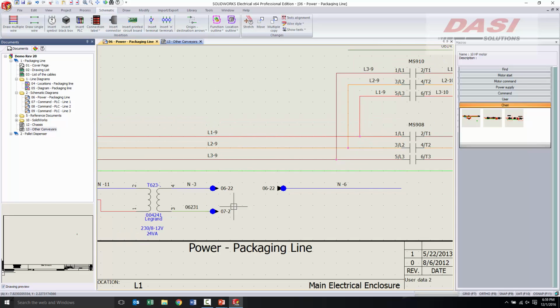Say you had that terminating into some sort of contact that was going into an IO piece. Yep. Say you wanted to move that contact down to the 3rd input instead of the 1st one. Would that automatically change your cross references? No, not unless, because that's in the circuit itself. Your circuit designation would change, not the wire going to that connection. You would have to change the wire location. But if you change that wire down too, it would automatically.